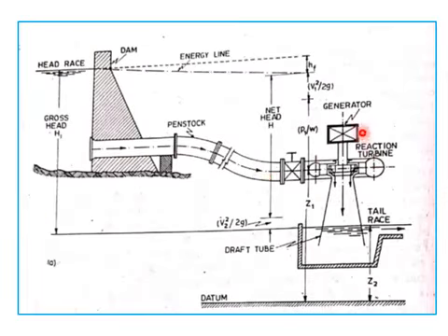This is the case of a reaction turbine, where again water is brought from the penstock, but there is no nozzle fitted at the end. That means the water is taken in through the casing. Water is brought from the casing to the guide vanes and then taken into the runner. As the water flows in the casing, the change of pressure from pressure energy to kinetic energy takes place.